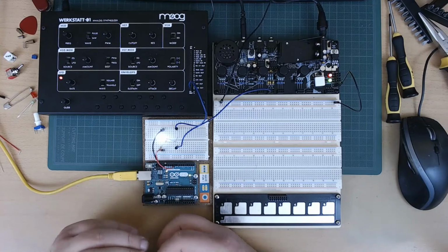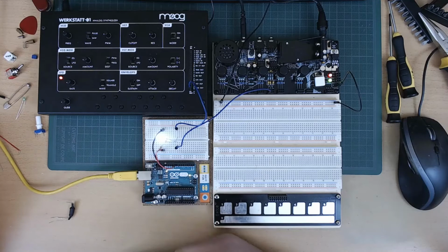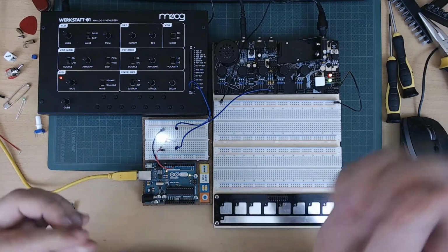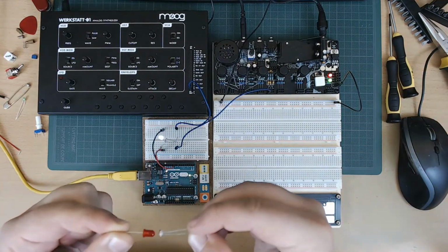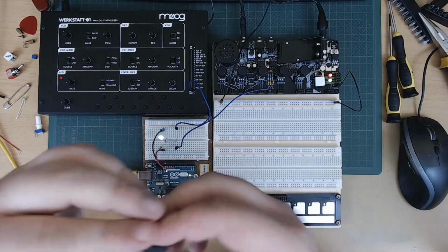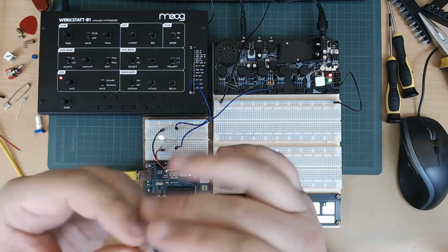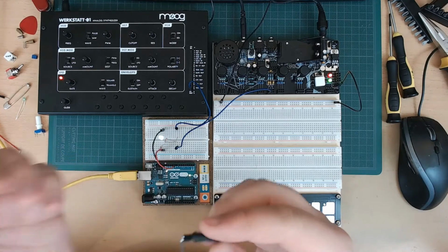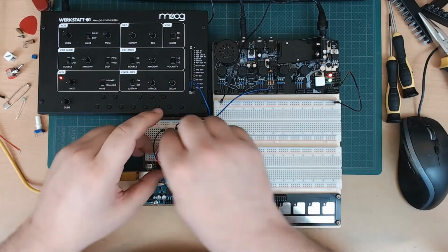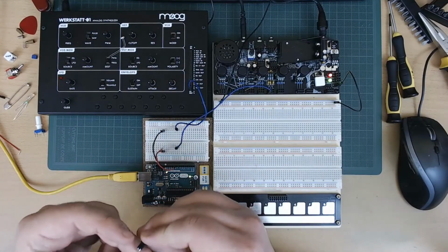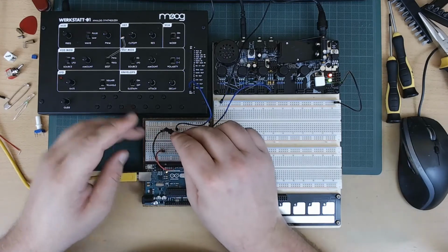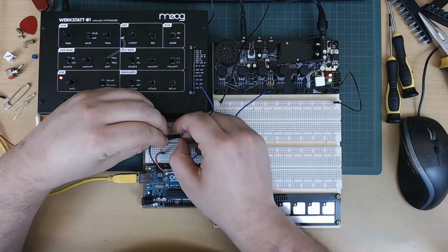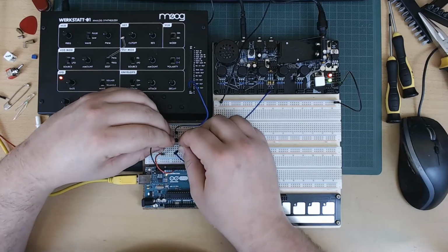Now, a more convenient way of doing this with an LED and a light dependent resistor, where you need to cup the resistor to get an effect, is to take a light dependent resistor and an LED, put them head to head, put heat shrink tubing around it, and then you get this. And this is a homemade vactrol that I made. And inside this, you get the LED and the light dependent resistor in a dark enclosure, which means you don't have to put your hands over it anymore. And if you have fingers that aren't as fat as mine, so you don't struggle with wires.